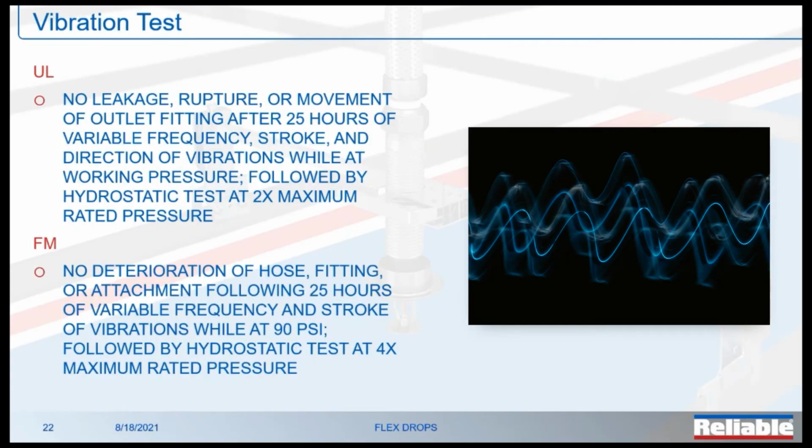Again, FM a little less on the vibration. Similar setup, again, down to the vibration table. They don't go into a lot of detail about side to side, up and down, and all that. But they do require a 4 times rated pressure hydrostatic test rather than the 2-times after the vibration test.